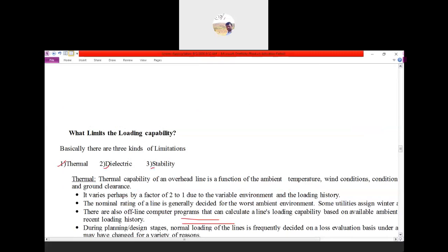Due to the high impedance, the load falls on generator B. If you apply more power flow here, we can reduce the power in generator B. This is without considering the FACTS devices.